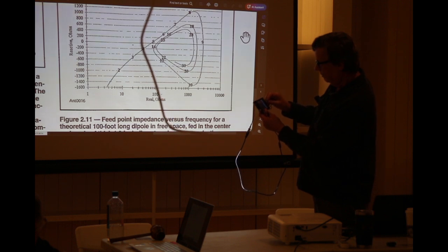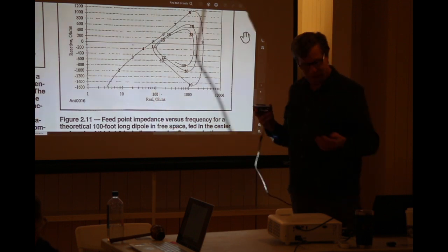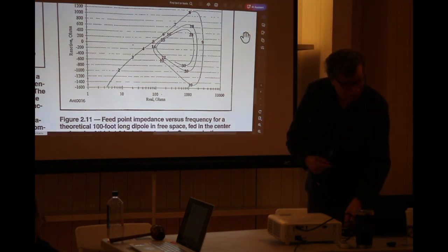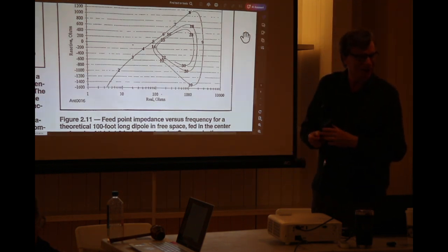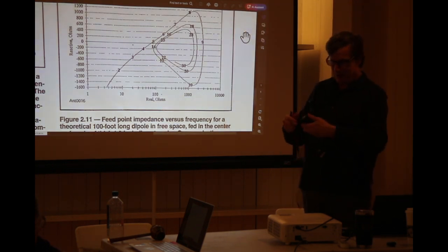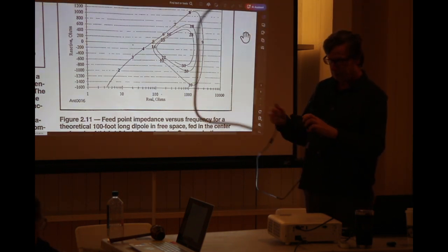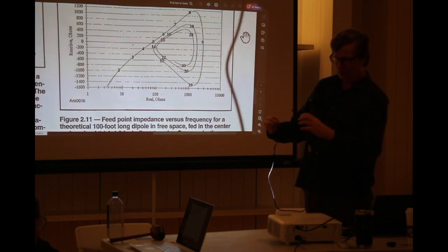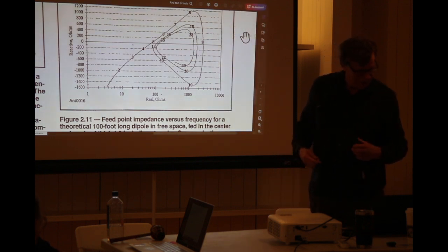Is that 50 ohms you have there? That's 50 ohms, yeah. Okay. But you can do it for any impedance. Yeah. So if I have a 600 ohm one as well. You want to have them as non-reactive as possible. Now when you start going up to microwave and stuff, you're going to have to be a little more refined. But anyway, now we have a calibrated system, and whatever we put at the end of that will be correct.